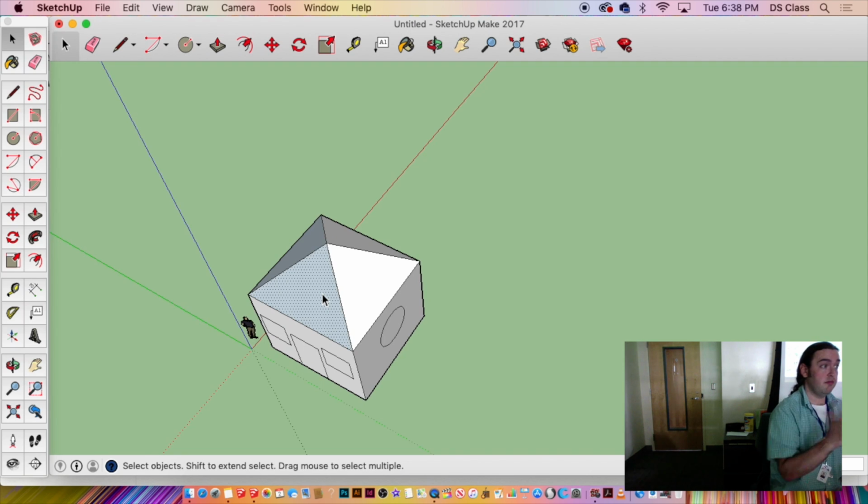They have to have an obverse and a reverse. So gray is actually inside, whereas white is outside. If you have those things mixed up, it becomes very erratic in the printing. It can exist perfectly fine inside the computer, but when you try to print something like that, big problems.